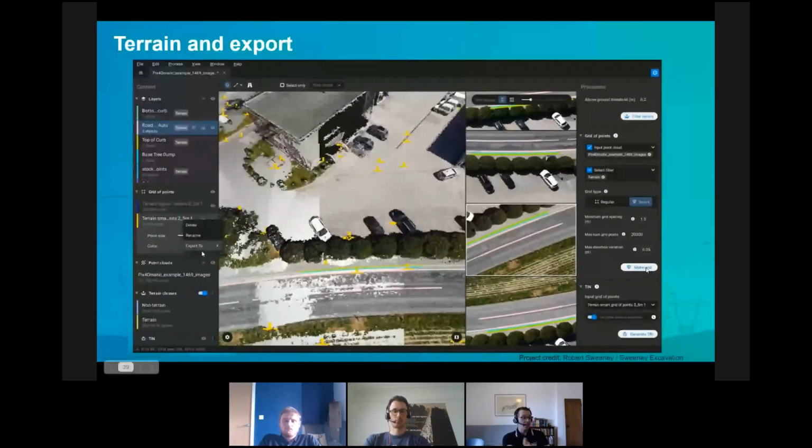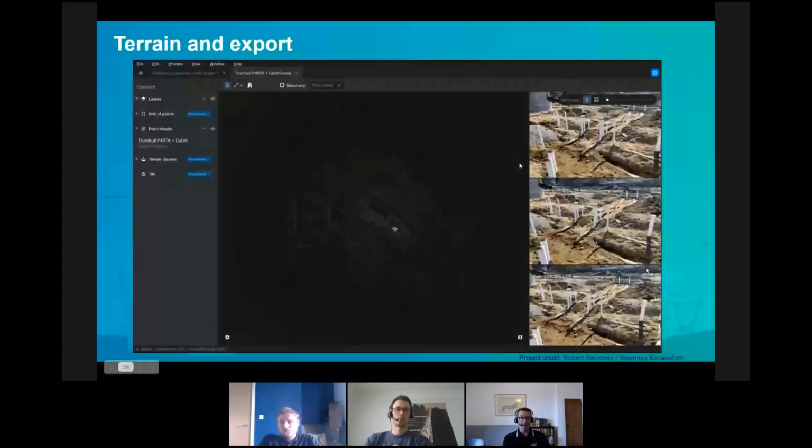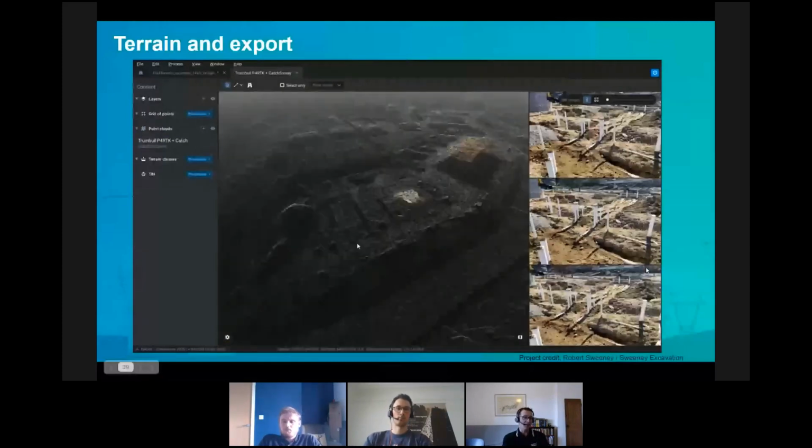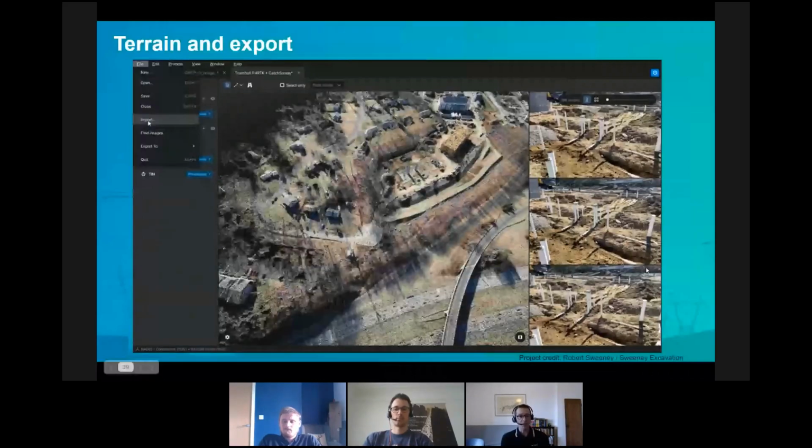And in fact, if you want to send out just your grid of points, it's going to be manageable, because in this case, you can see it's 20,000 points. And we all know if you give 20 million points to Civil 3D, it's going to have some issues. But if you send 20,000 points off, you'll be on your way in no time, and it'll be super manageable. So I think that'll really help you quite a lot.